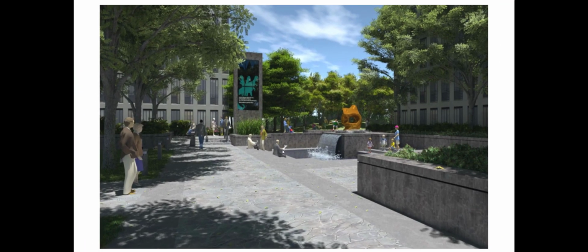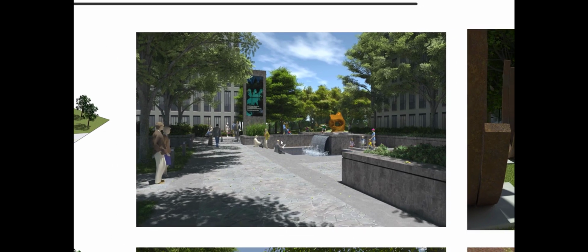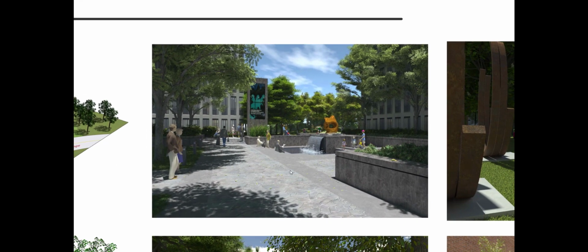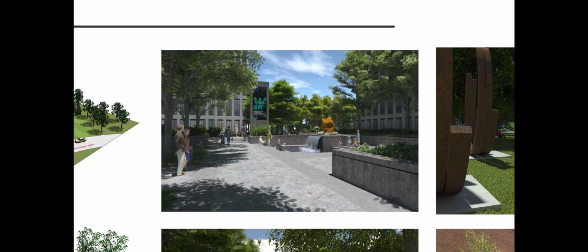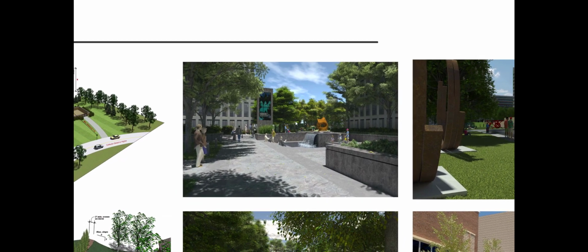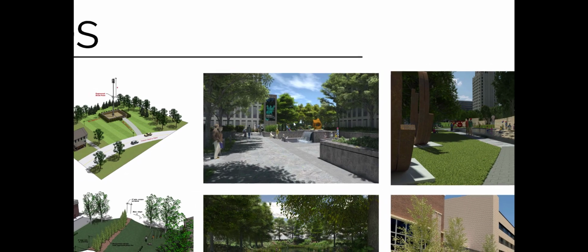This is actually a rendering from view, but it kind of shows the kinds of things. In this case, this was an example where I scattered some leaves around, again, to show it perceptually realistic. It's not, there's like this time of year, the leaves are still in the trees, but they're starting to come down. That's a normal part of our perception of spaces. And you can do that in SketchUp with the scatter plugin. Just make a few leaves and it can scatter them around randomly.